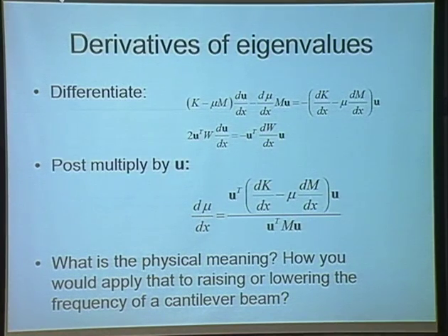So relatively speaking, doing derivatives of vibration frequencies by finite differences is not smart. In linear structural analysis, the relative gain is smaller. That is, you can essentially calculate thousands and thousands of derivatives for the cost of a single analysis.